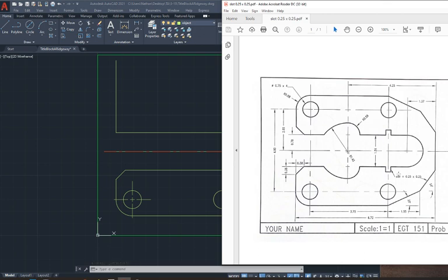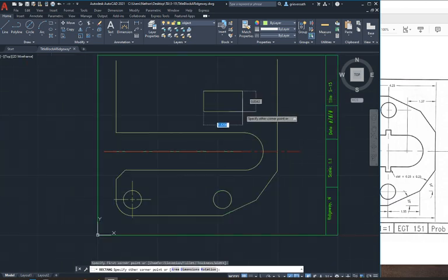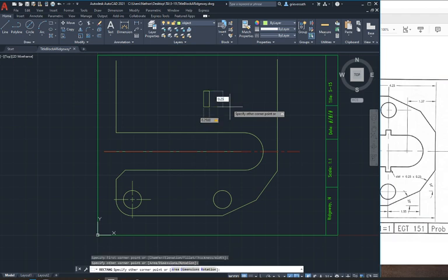So next we have these slots. These slots are squares, and they are 0.25 squares. So let's just go over here and use a new tool. Let's use the rectangle tool, because we've not used that one before. And then we can specify the first corner point. We're just going to select absolutely anywhere, because we're going to be moving this. And then now we can tab between the two sides of the square. So 0.25, tab over, 0.25, and there we go.